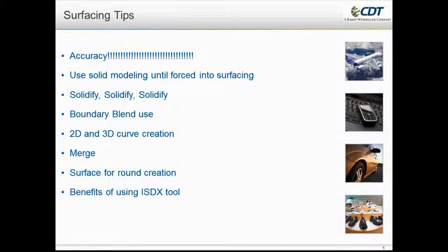It is much more detailed in its thought process. At any point in time you can build most things in solids, and for the very few details that you need to put in, you do it in surfacing. That really should be the thought process for doing surfacing work. There's very few times that you should be doing entire models out of surfacing work.